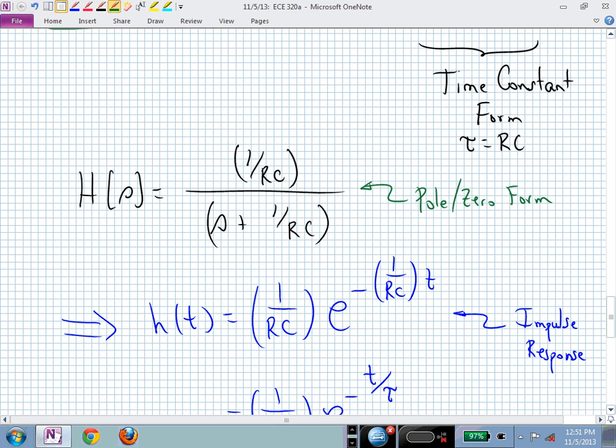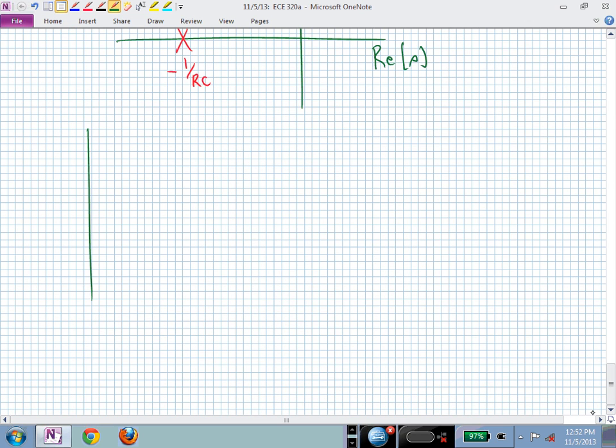If you put in a constant input for X, what are you going to see at the output? After the transient, you'll just see X, won't you? So you're going to have this direct connection, essentially, between the input and the output. So the DC gain is 1 in this case. For a Bode plot, we're going to be sketching 20 times the log of the magnitude.